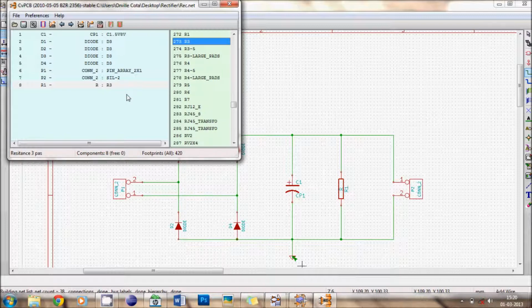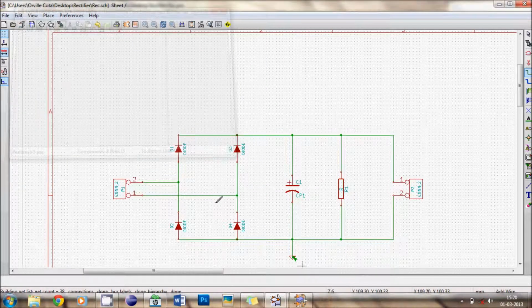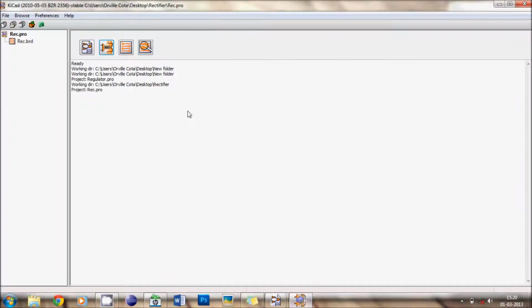Now all the components that we required with the actual dimensions we have given. The ground, it's in the terminal part, so we don't have to give a separate ground. Now what we do is we save it. It will ask for a place, the created folder will save it. That's it with the second part.